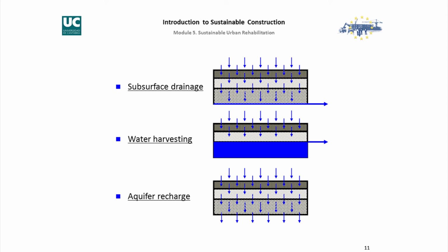For example, in Mexico City, when we take a lot of water from a natural aquifer, the land even decreases the level, and we have a serious problem because of the impervious surfaces. The natural recharge disappears. So with these techniques, we are able to maintain the natural recharge of the aquifers, and this is very, very important.